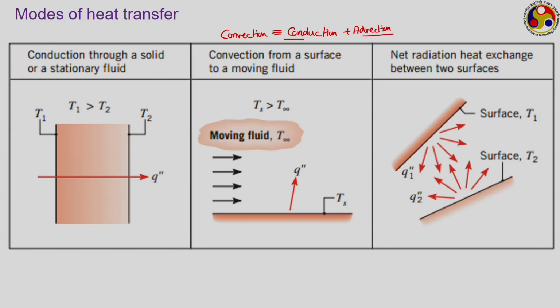Now, conduction is associated with the energy transfer because of the temperature imbalance from one part of the system to the other part. Any solid, liquid or gaseous substance can participate in conduction heat transfer. Though it is mentioned here as only solid or stationary fluid, conduction is a fundamental phenomenon and any system can participate in this. It may be more pronounced in case of solids and very insignificant in case of gases, but conduction is always there. Whenever we have a temperature gradient across a particular system or across the same substance, solid, fluid or gaseous, there will always be conduction.